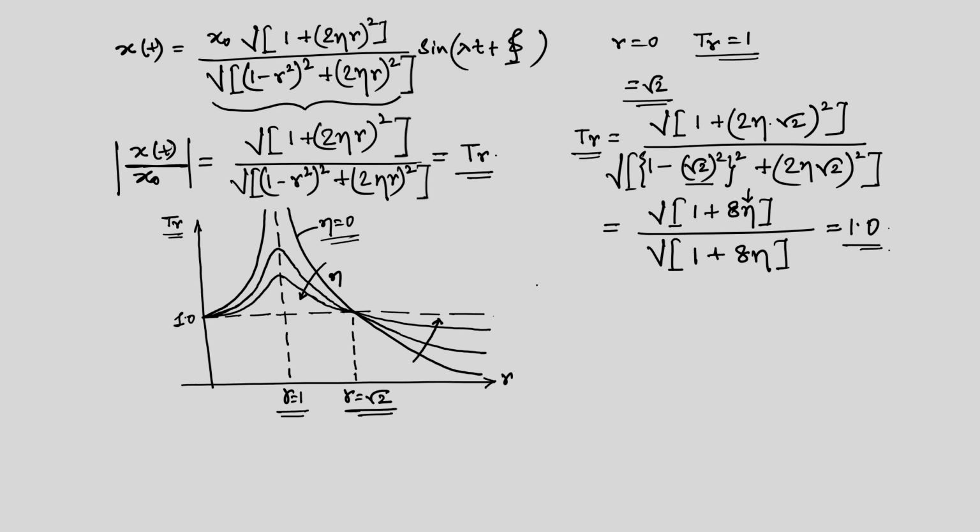In case of dynamic magnification, the behavior was not like what we observe here in this plot of transmissibility. Okay. Now, recall the equation in this case. What we have? We have m x double dot plus c times x dot minus x s dot plus k times x minus x s is equal to 0, right.